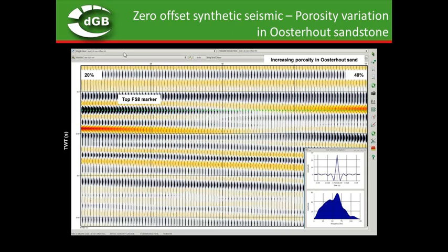In the same way, you can browse, and that's where I go back to another question that just came in. You can browse into the various rock properties from the pseudo-wells, and this you can do in 2 ways. At the base of the SynthRock window, you see the rock properties in depth. So you see the pseudo-wells one next to each other. And there is a similar combo box that allows you to browse through the various quantities in depth, displayed in continuous cross variable density. Also, at the same time, you can display your rock properties from the pseudo-wells converted from depth to time by using this menu variable density view. It would allow you to see the interpolated rock properties behind the wiggles, because in this view you see first a wiggle display and a variable density display, which can be one of the rock properties of your layer model, of your simulation.